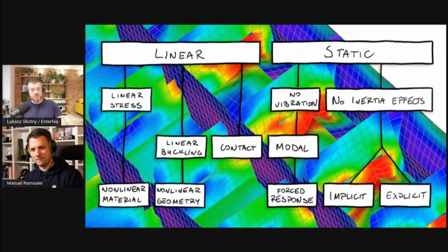It's a fact that in some solvers, depending on how they have their user interface written, you could run a linear analysis with contact, which would make it a linear contact, and then a nonlinear analysis with contact would be a nonlinear contact. Or does the contact have to change to be linear or nonlinear? Nobody knows. The reality of contact is that if you have two elements in your model and they can touch, sometimes they will, sometimes they won't. That's nonlinear.